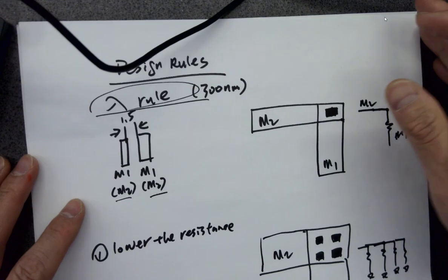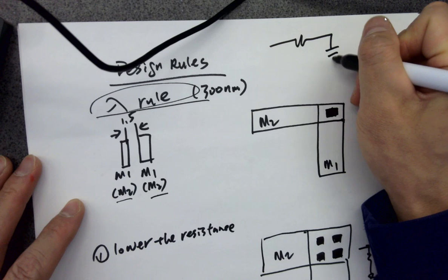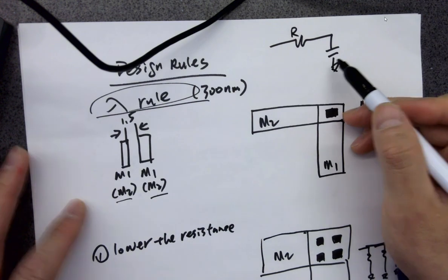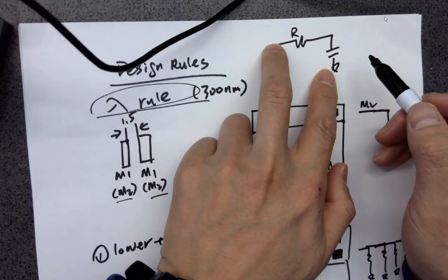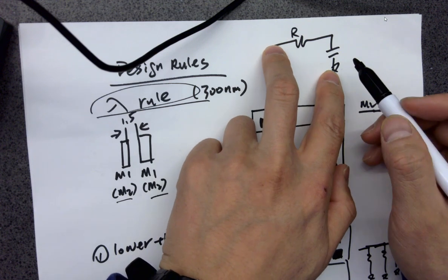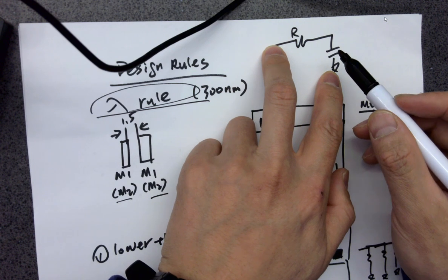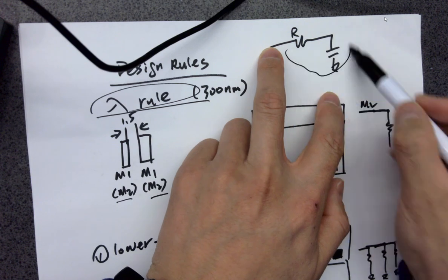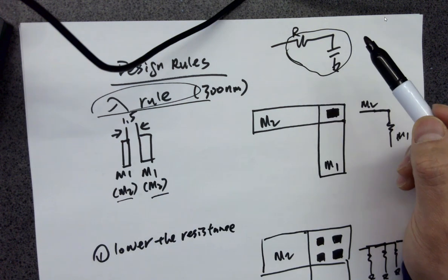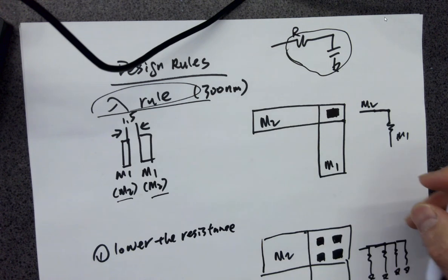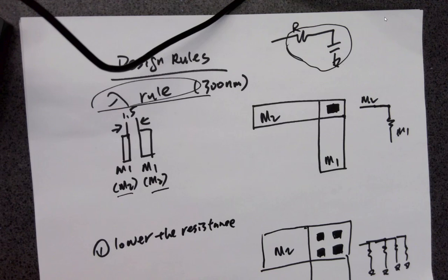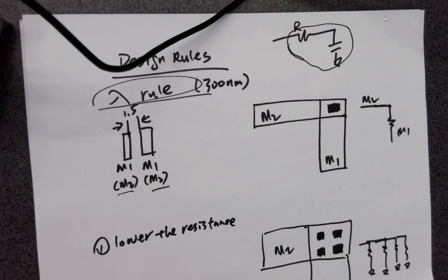So for the digital chips, we have learned the RC circuit, so we know that if you have a different resistance, it's going to cause a different time delay, right? If we're trying to deliver the same clock to two different circuit blocks, but eventually they receive it at a different time, there will be issues. So time delay could be a very important thing to consider. And a lot of times when you are doing a PCB design, we ignore that resistance issue as well. But just let you guys know, when we are doing a PCB, the trace resistance is also very significant.